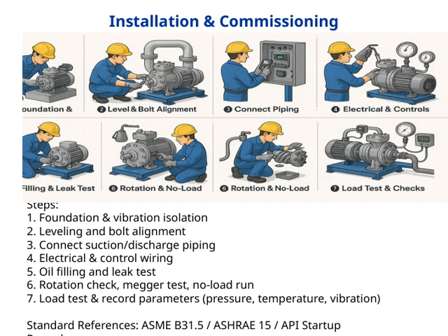Then, we connect the suction and discharge piping carefully, making sure all connections are secure to prevent leaks and maintain system integrity. After that, we handle the electrical and control wiring, ensuring all connections are correctly made according to standards to guarantee safety and reliable control. Once the hardware is in place, we fill the system with oil and perform leak tests to confirm there are no leaks and everything is sealed properly.